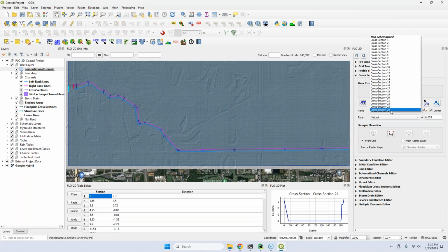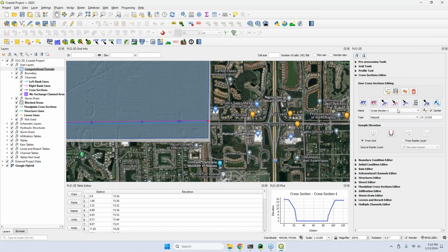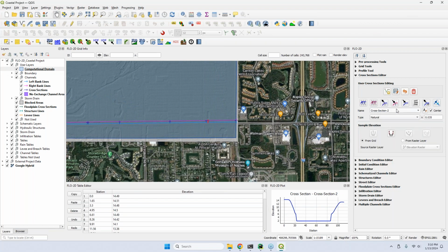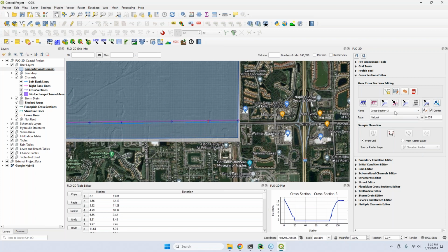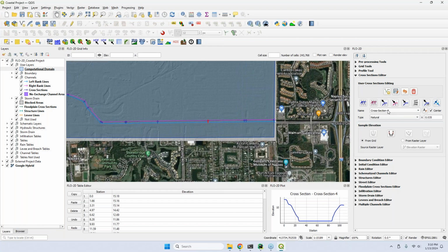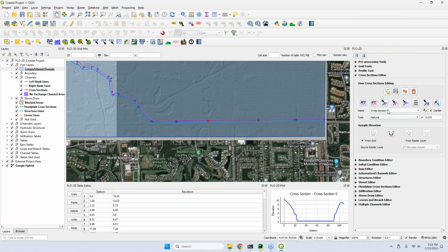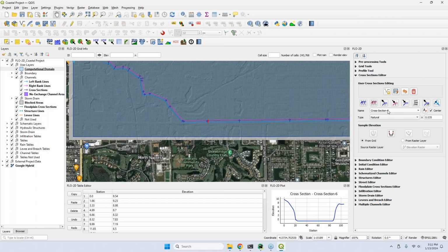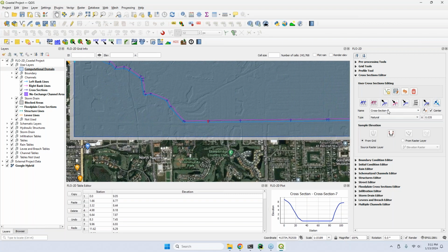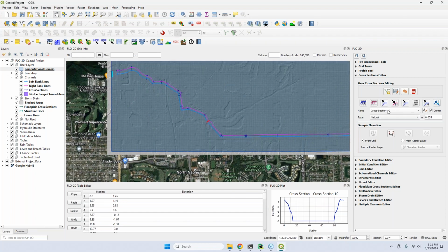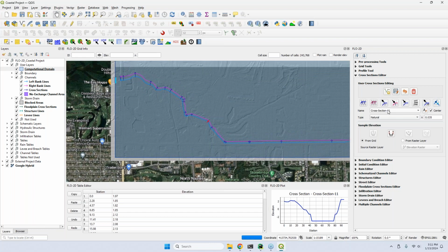And now the next step in this process would be to check and make sure that all your cross-section data is good. So we go back through this, and now this time, rather than clicking and selecting these from this list, I'm going to use the roller wheel to scroll through these. And all I'm looking for is to make sure that these cross-sections change geometry as they go downstream. This roller wheel's a little touchy, so I'm trying to be careful. It doesn't have very good haptics. I can't tell when I've rolled enough.